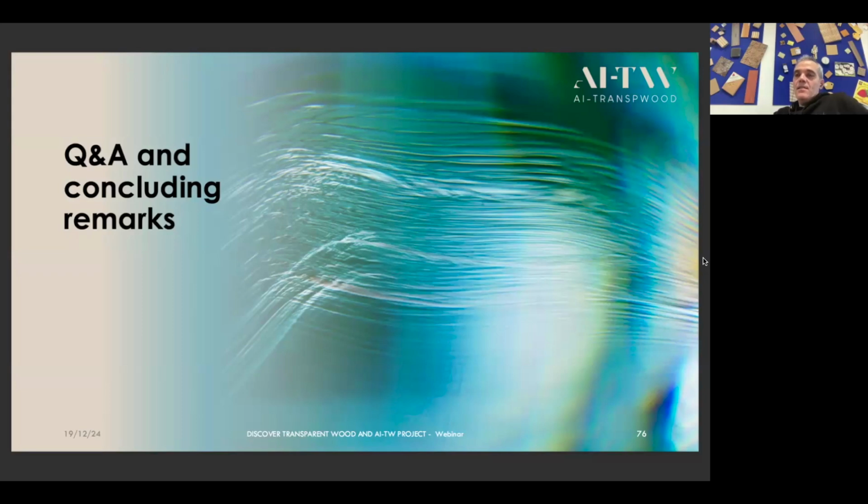There's another limit concerning the fact that when you infiltrate a resin, you should select it in the most appropriate way. That is to say, the refractive index of the resin should perfectly, or really quite perfectly, match that of the delignified wood, the treated modified wood. But this is possible only when you are able to measure very precisely the refractive index of the delignified wood. And this is still not very easy to perform.